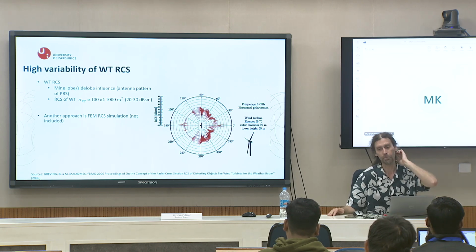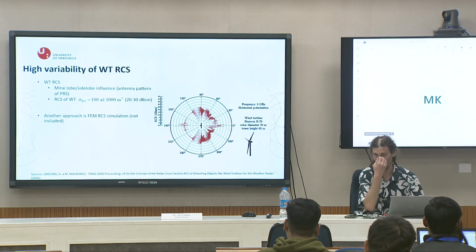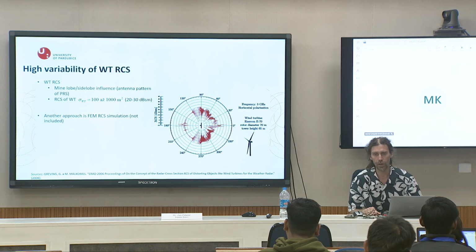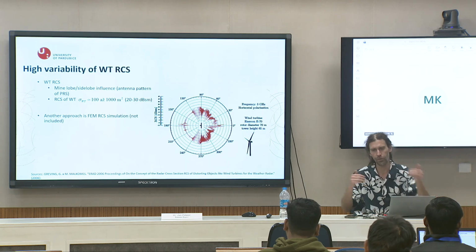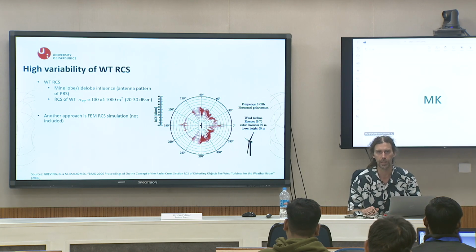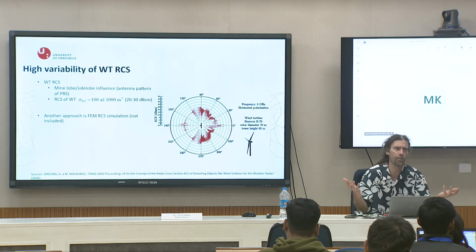How could you measure RCS generally? You probably know that it is done in an anechoic chamber. We have some experience with measuring the RCS of UAVs, because we have an anechoic chamber of about 5 by 5 by 5 meters. So we can measure some smaller objects, and for a UAV it is not a problem.